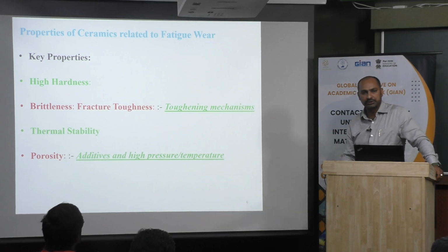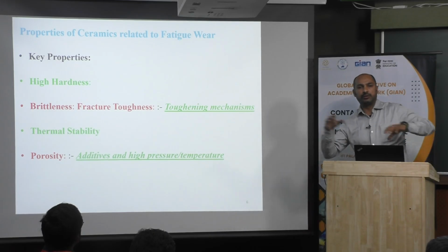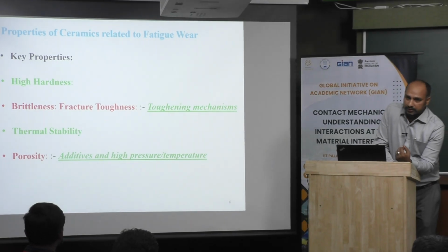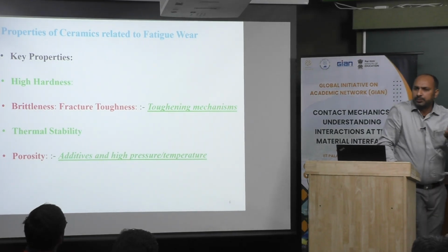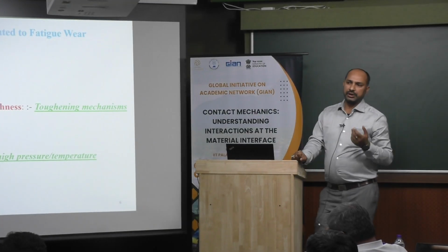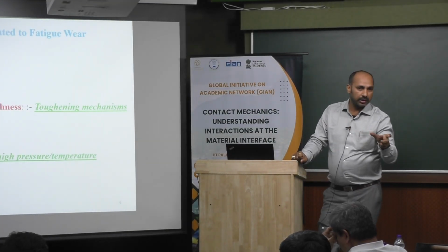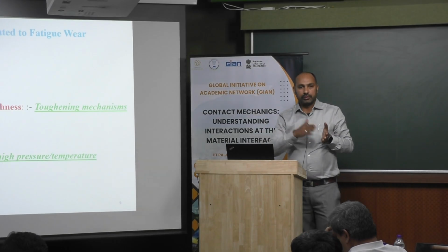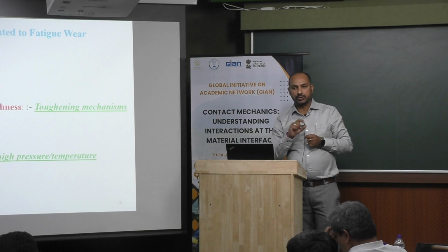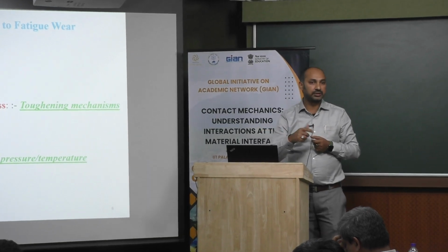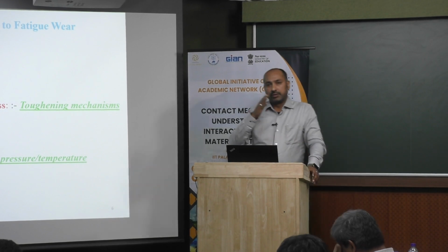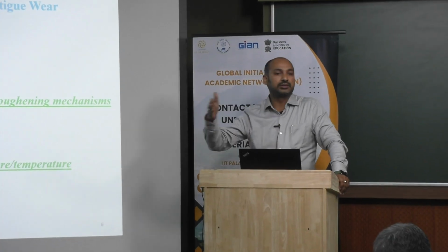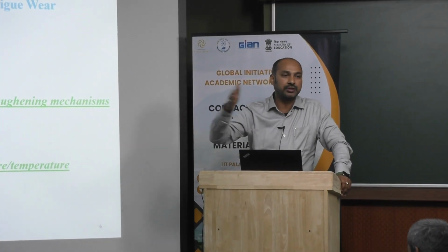In ceramic you will have multiple pores inside, which can be considered as crack size, and that could be of critical size and it will fracture. So in ceramics, we consider that cracks are available. Now the cracks should not propagate fast. So for ceramics we have to consider fracture toughness instead of toughness or other properties, because cracks are always there. How fast these cracks can propagate, we have to hinder.